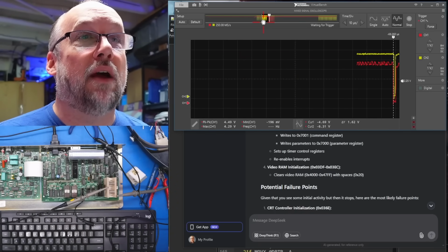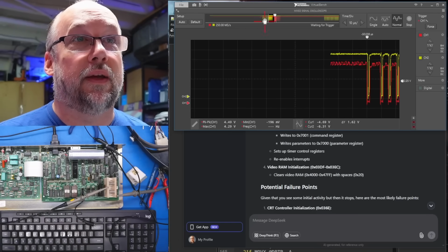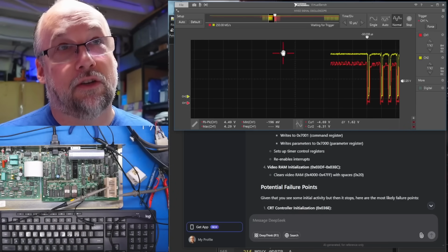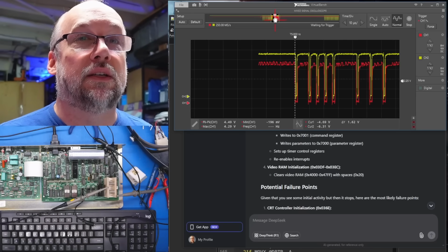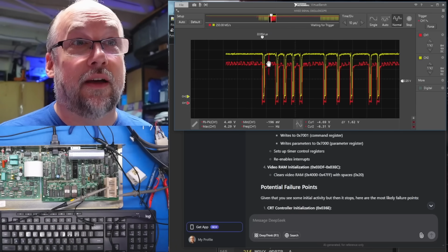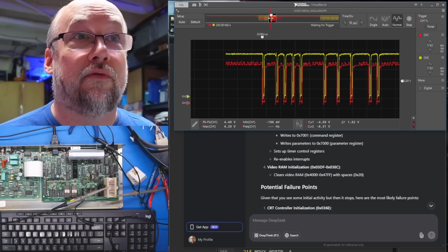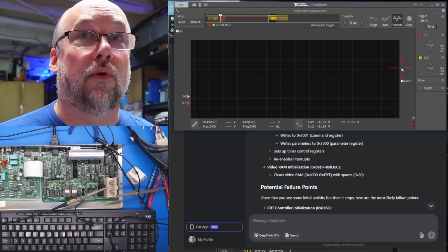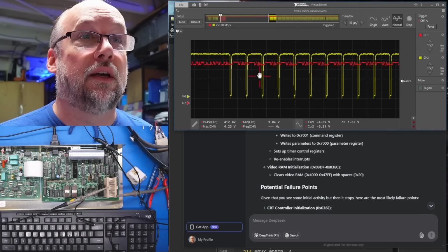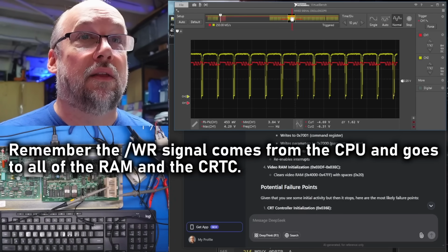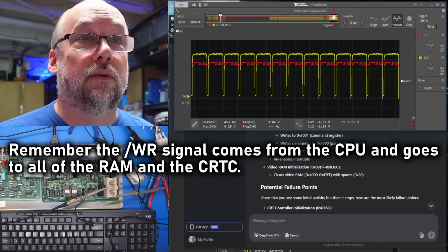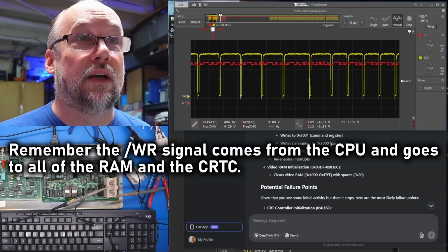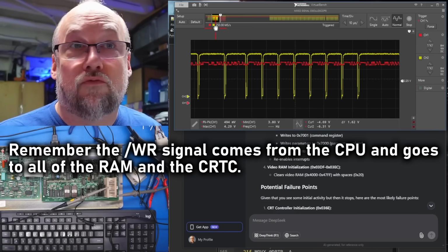And you can see right before the trigger, and I know it's not visible here, but we can see it up at the top, that there are some writes to something else. So something else is being written to before it actually writes to the video chip, because the video chip is only selected 11 times, and then those write signals are going to be intended for the video chip. And then we can see further on in the code, it's doing a whole bunch more writing. I know we don't see the waveform here. Actually, maybe if we turn this off and on, we might. Yep, there it is. Okay, so we have some more writes that are happening to something else. To be honest, I don't know why it was only showing us that little snippet where it's writing to the video chip. But anyways, that stuff is happening right before writes to something.